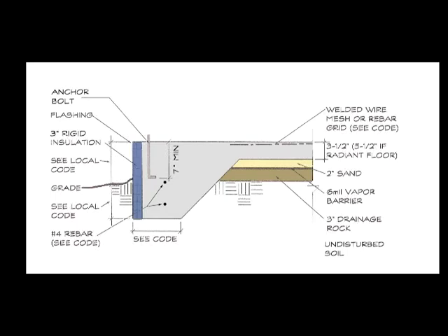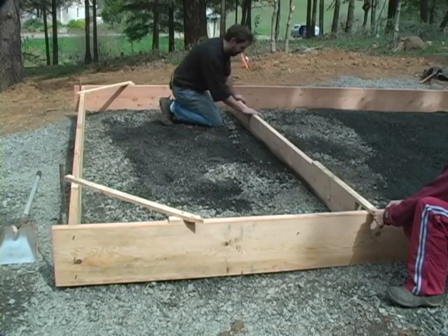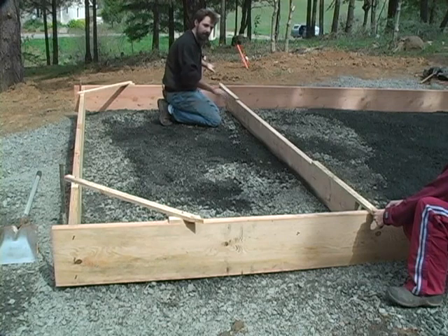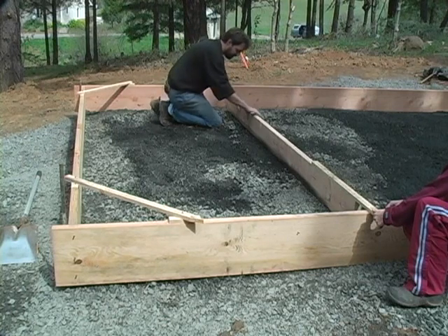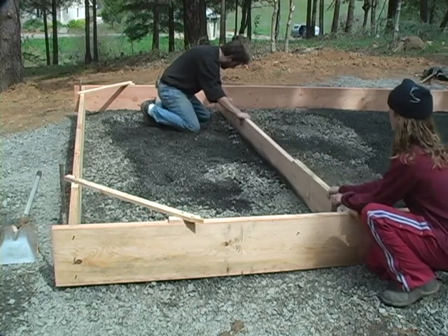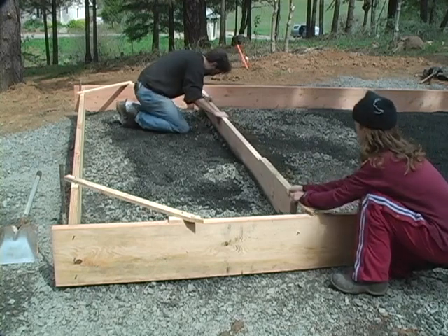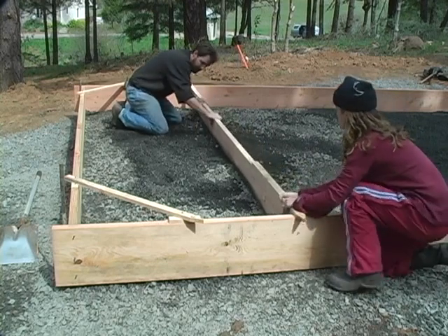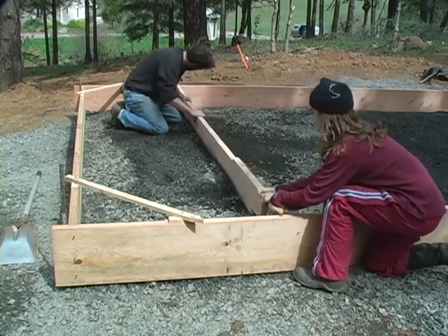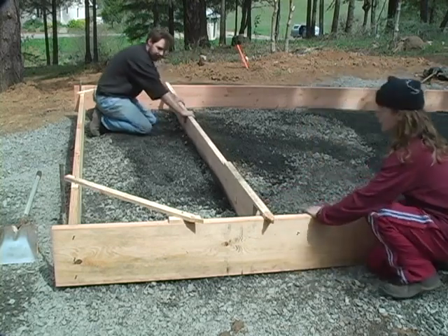So with our 3-foot stakes on top of the screed board extending out over the top of the form so we can slide it back and forth, we now sort of saw cut the surface to move high spots down and fill in the lows. Now some lows like we had right through the middle here are not that bad. We don't have to worry about them.